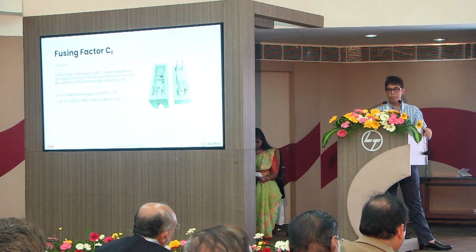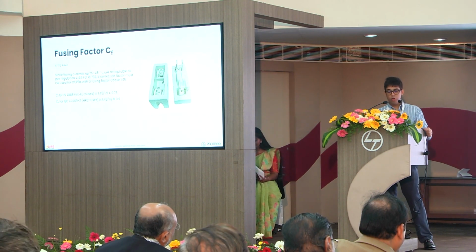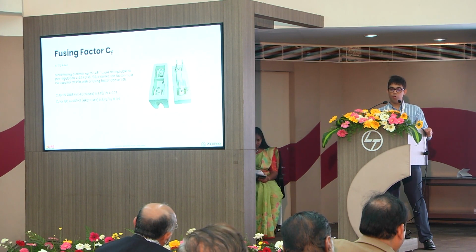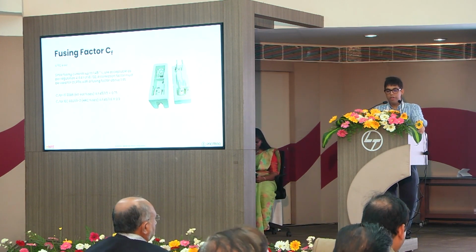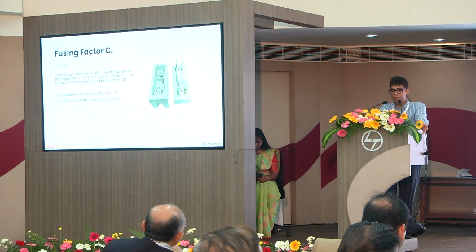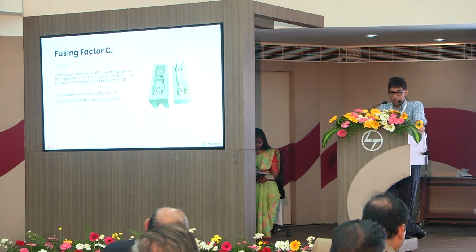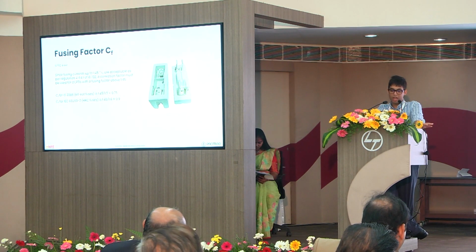So basically, how do you come up with these derating factors? You have to refer to the product manufacturing standard or ask the manufacturer what the conventional tripping current is. Since we are allowing fusing currents which are up to 1.45 times In, as per 4.4.1 of 732, anything with a fusing factor over 1.45 has to have a correction factor applied.